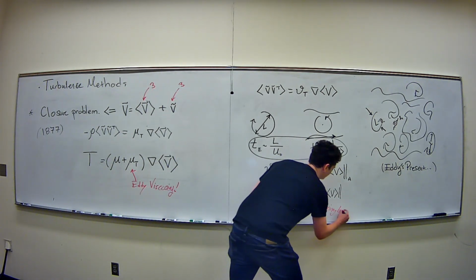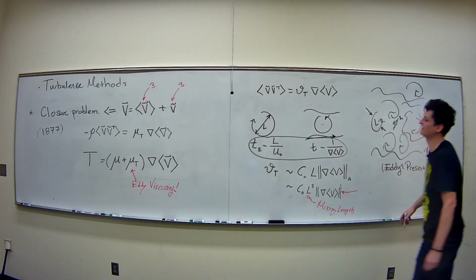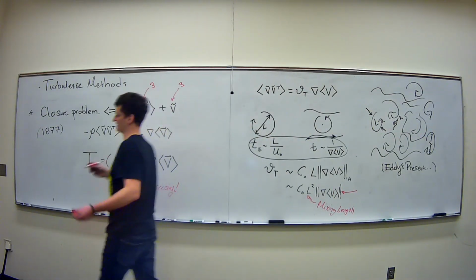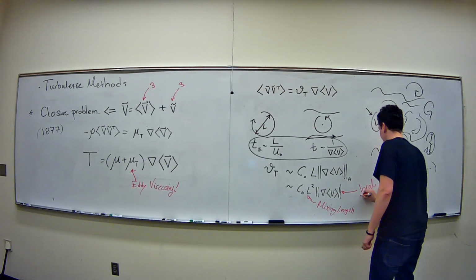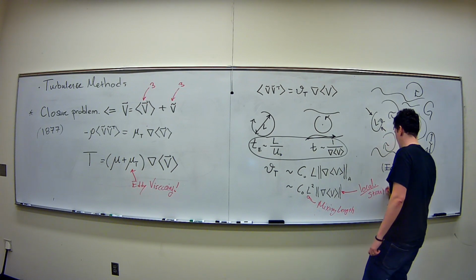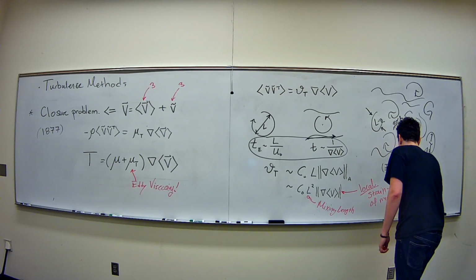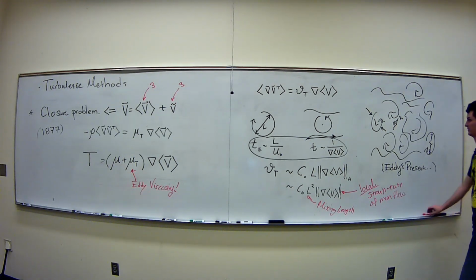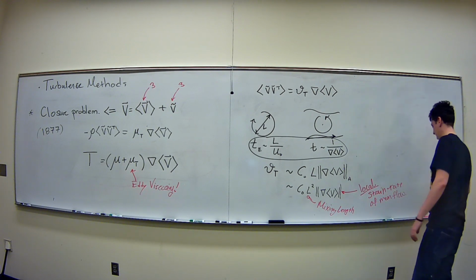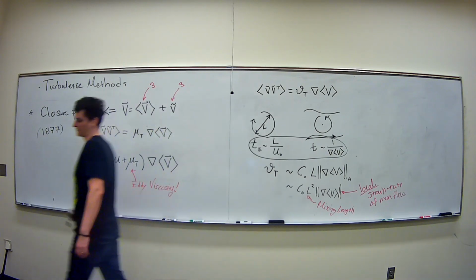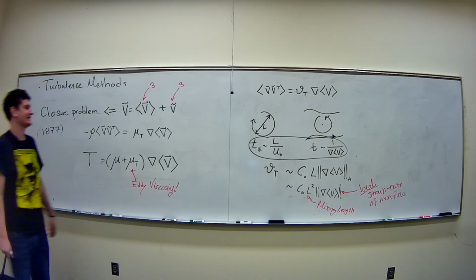Okay, and importantly for this whole theory, I want to add the idea that this eddy viscosity is a local property. It has to be by the scales. I was really just trying to get, okay, here's your local property of the mean flow. Local being important. Critically importantly though for this eddy mixing length scale is that it's a local property.